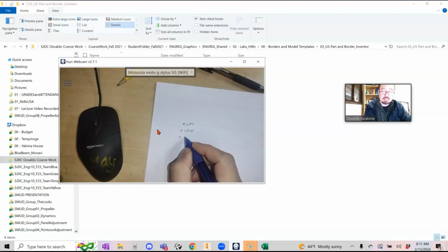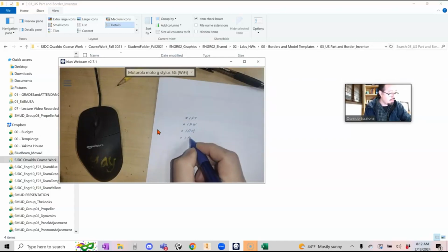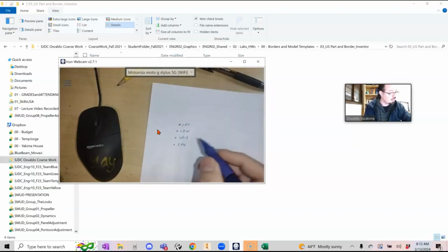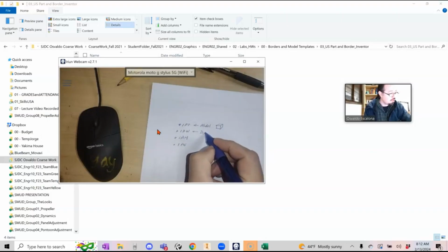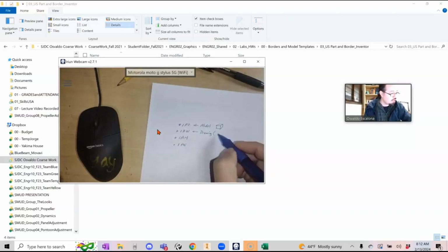You actually have more. You have the IAM, and you have the IPN. The IPT is your model, and if you install Inventor at home, it will look like a square, like a cube. Your IDW will be your drawing, which is your electronic drawing. This is the one that will communicate with Inventor when you're making a drawing. You create a model, then you drop it into the drawing, and then you annotate the drawing.